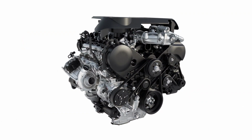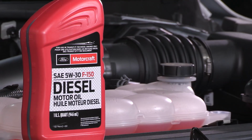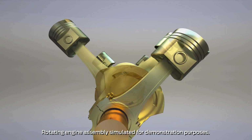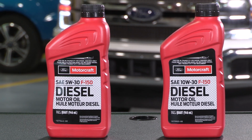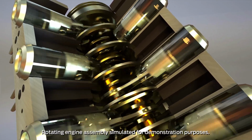Because the 3-liter diesel is smaller with lower operational loads than the larger Power-Stroke engines, and it has been designed to run on this lower viscosity oil, the oil will maintain the appropriate oil film thickness to protect the engine. The lower viscosity oil supports fuel conservation because the engine doesn't have to work as hard to pump the thinner oil through the engine or move the lubricated engine components like the engine crankshaft spinning in the bearings.